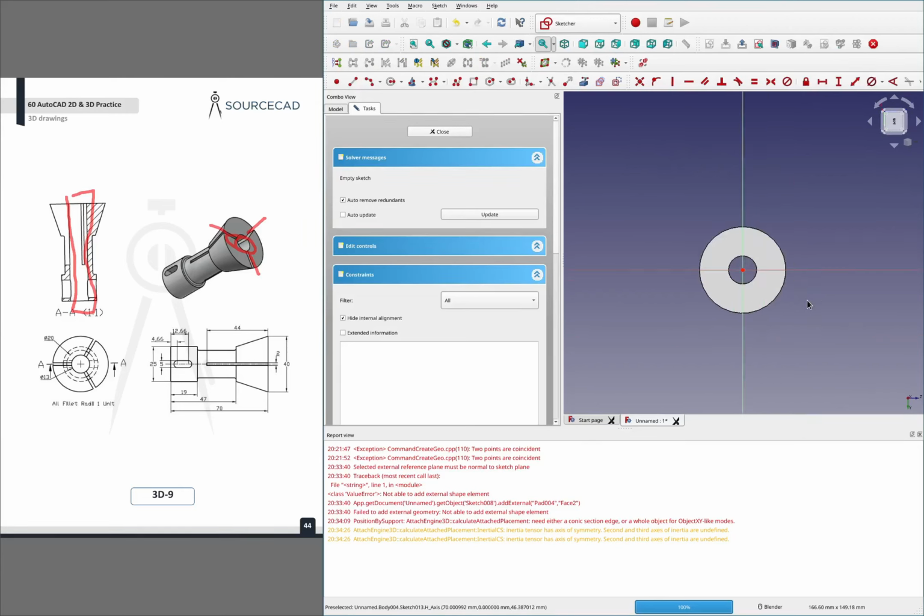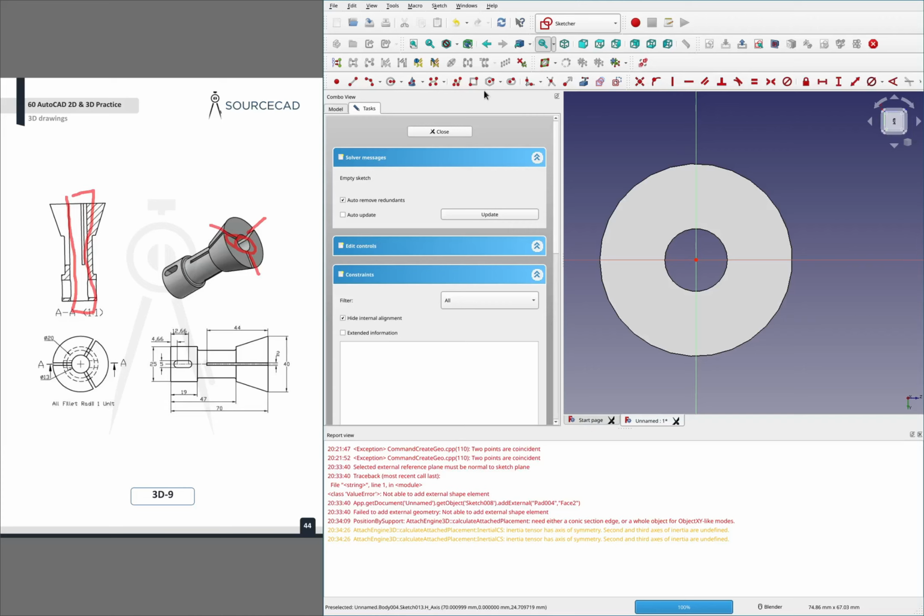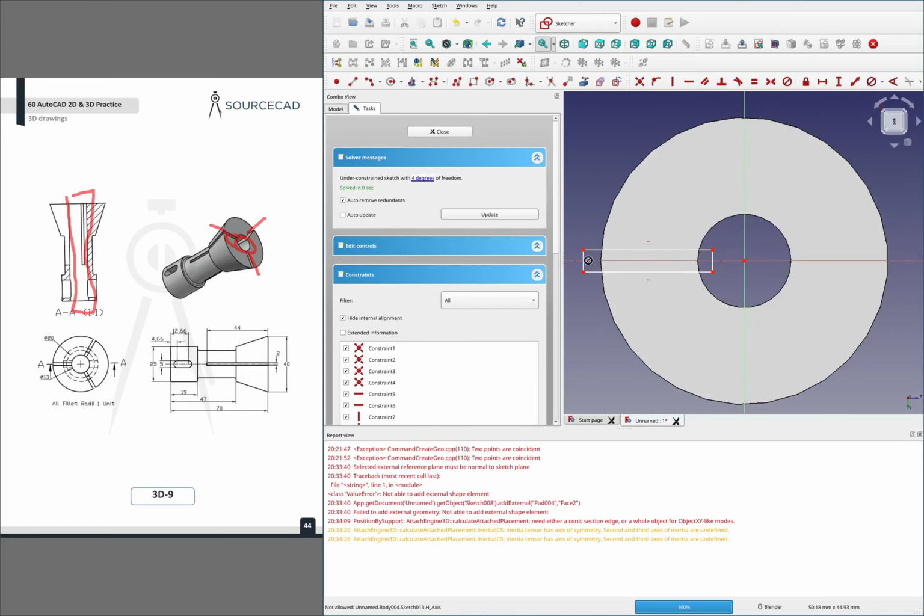Okay, come back to this face, a new sketch, and then let's see. Yeah, so we've got a cut here, and I'm going to grab the symmetry tool, make this symmetrical around that, and then the width of this, let's see, is right here at 2.